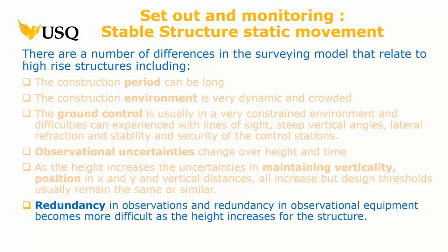Now you should have seen, as you've done more and more least squares, that least squares thrives on redundancy. Without redundancy, least squares is just a simple mathematical formula, right? The more redundancy you have in least squares, the better it is. Mind you, in the last assignment where some people said you should be reading the angles 18 times, that probably was going a little bit too far. It's a bit too much redundancy.